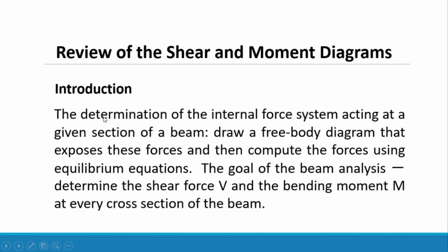Introduction. The determination of the internal force system acting at a given section of a beam. Draw a free body diagram that exposes these forces and then compute the forces using equilibrium equations. We will be dealing with summation of forces along y equal to 0, or summation of forces along x, which is also equal to 0, or summation of moment at a certain support or point and equate it to 0.